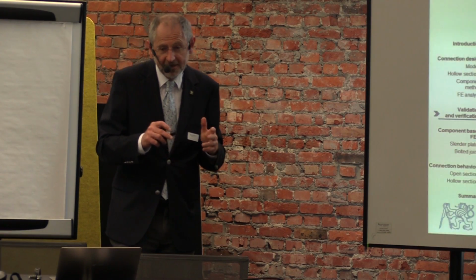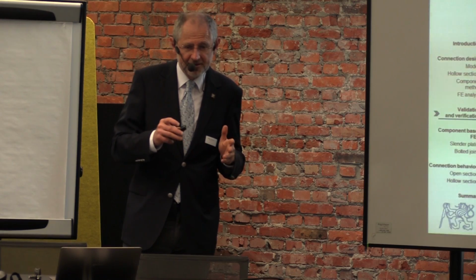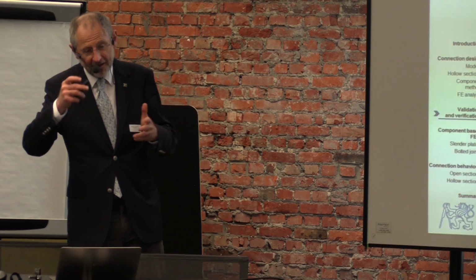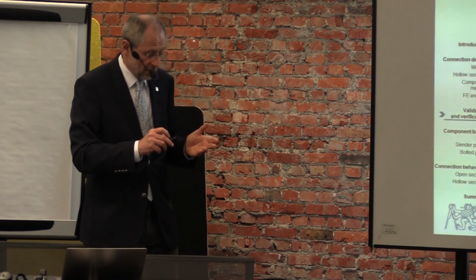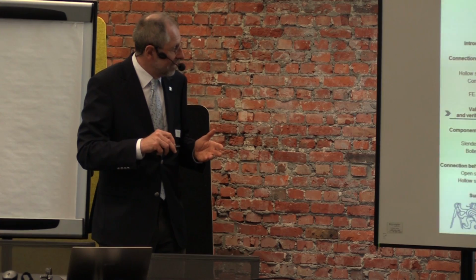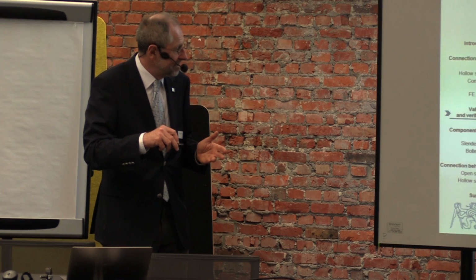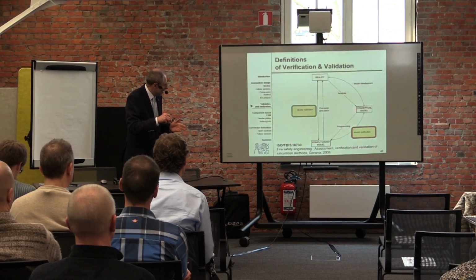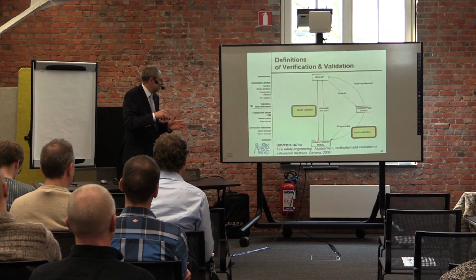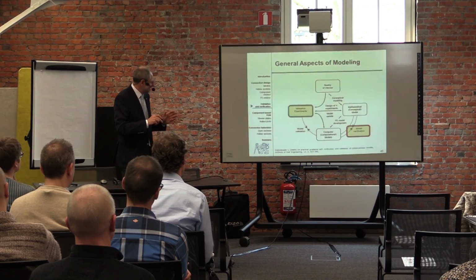In fire engineering it may be the nominal standard fire curve, or a zone model, which is a very simple two differential equation description of the energy in the fire and in the room. Then validation is between the reality and the computer model, and verification is between another model, a simple model or a more complex model, and the asked model.